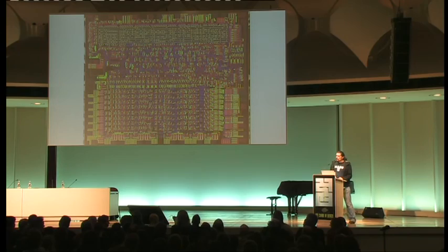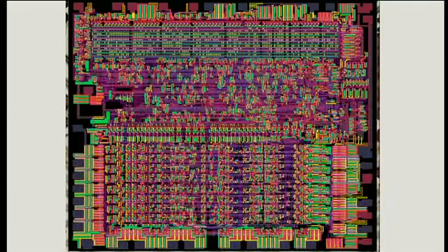So if you look at the intersections of all these traces and at what layers, at what levels they are, and understand NMOS and how this processing was done, from that you can derive the net list. And the net list is basically all the transistors and how the transistors are connected and how the nodes are connected to the transistors. And this net list alone specifies the complete working of the CPU.